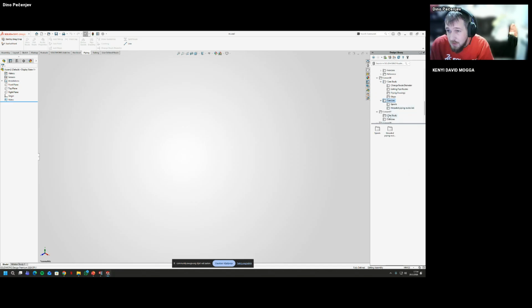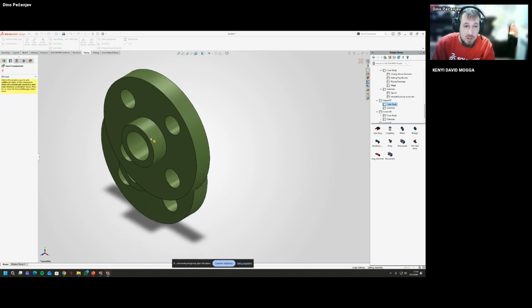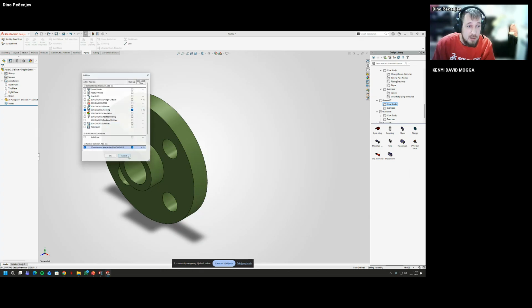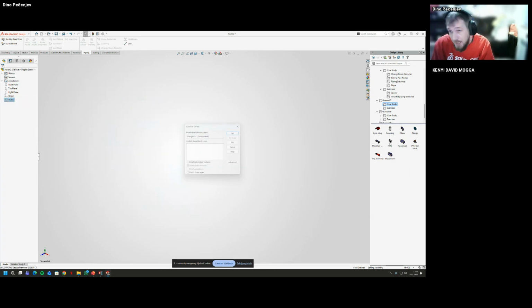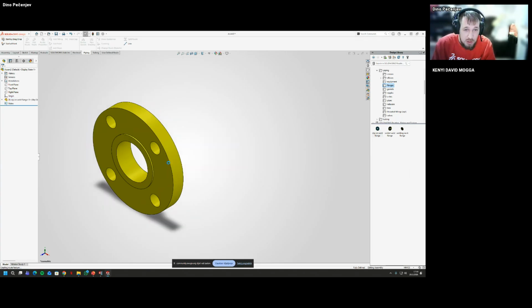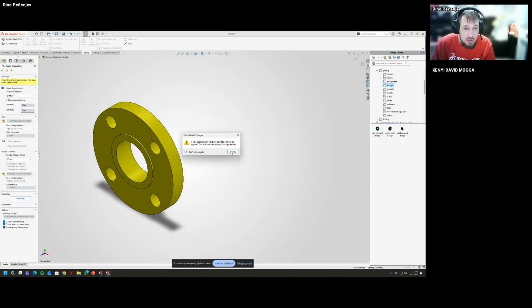So I'm going to use the flange here. I'm just going to drag and drop the flange. We didn't add it to the library, but I'm just going to use the 3-point weld flange. So I'm going to use the 1.5 inch. I can't use this one.